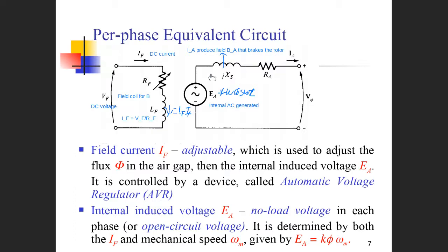So this is easy to understand. This reactance is more or less similar to the leakage reactance of the armature coils, but the function is slightly different. No current, and this function will be 0. As the current increases, across the synchronous reactance there is a big voltage drop.